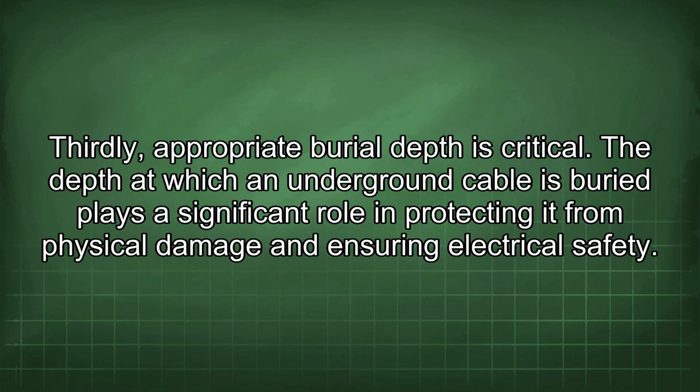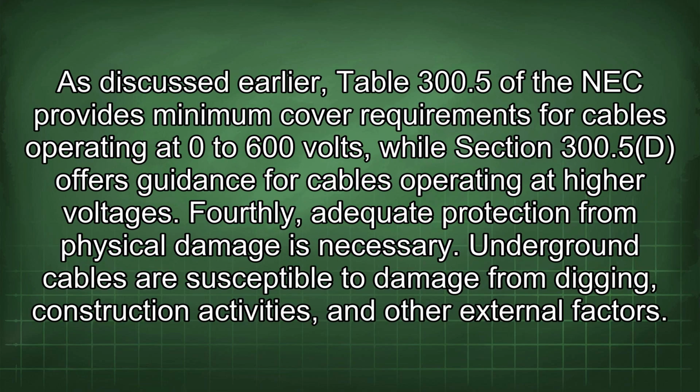Thirdly, appropriate burial depth is critical. The depth at which an underground cable is buried plays a significant role in protecting it from physical damage and ensuring electrical safety. As discussed earlier, Table 300.5 of the NEC provides minimum cover requirements for cables operating at 0 to 600 volts, while Section 300.5d offers guidance for cables operating at higher voltages.